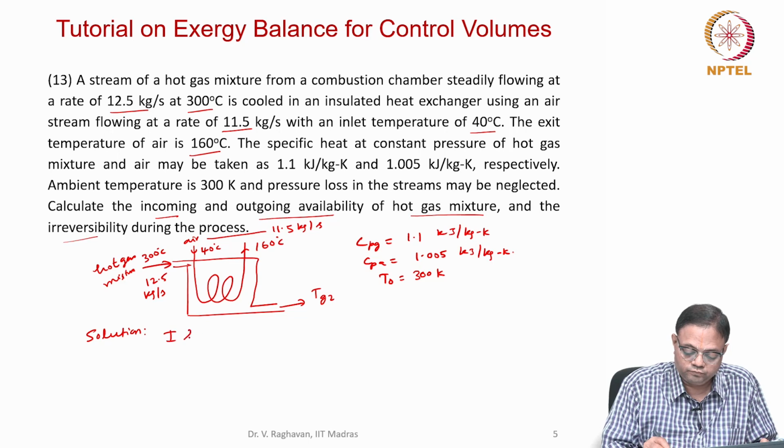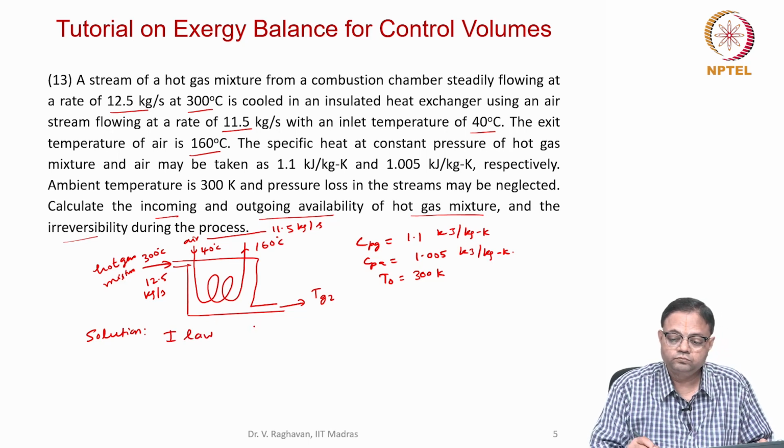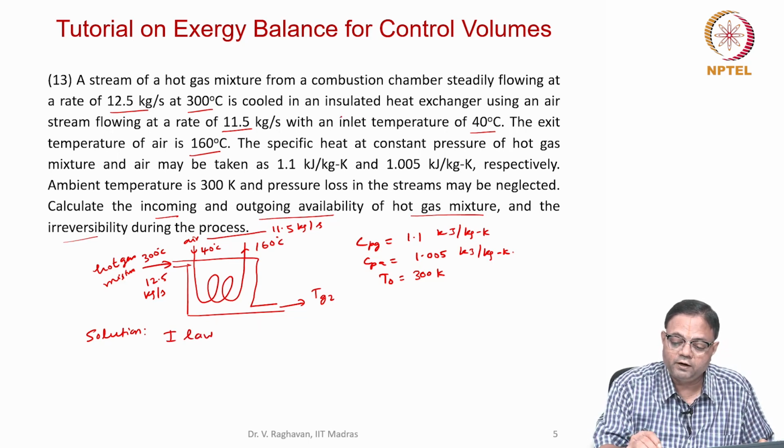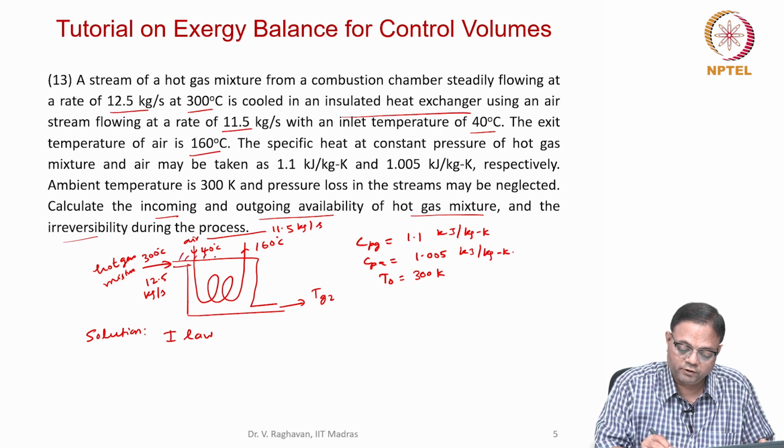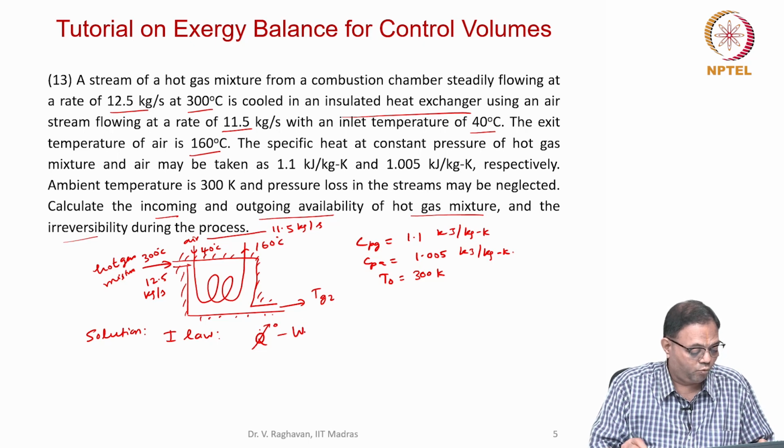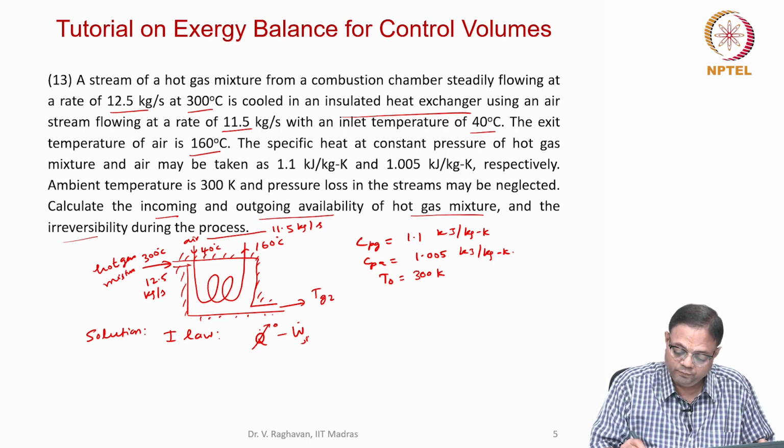First law. Here the insulated heat exchanger is given, so the heat exchanger is insulated. So first law, Q dot is 0. Similarly, there is no work interaction, so that is also 0.